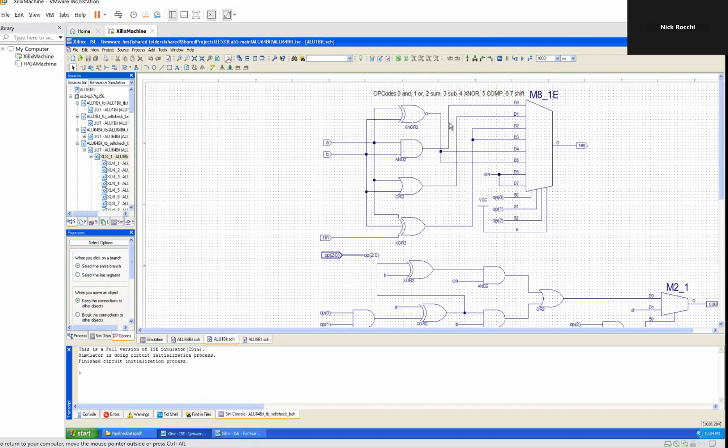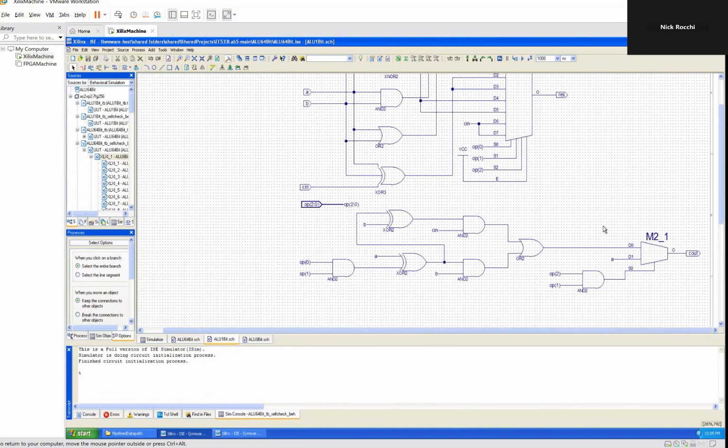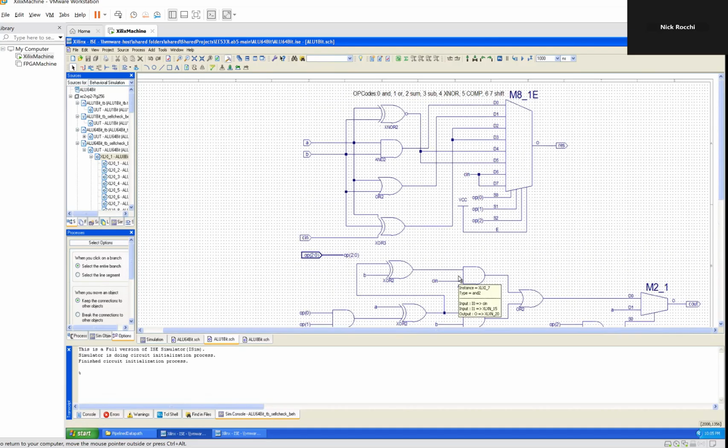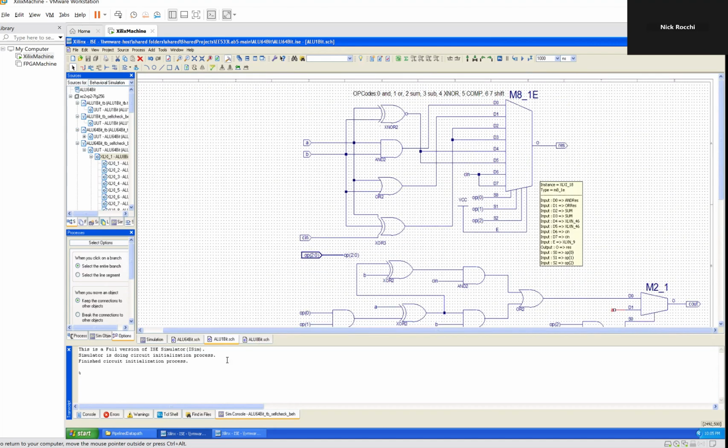We have all requested operations, as you can see. We take in 4 inputs, A, B, C in, and our operation, and output a result and a carry based on our needed results. It's worth noting that we have a setup here to see if we have a sum or a carryout for a sum or a difference of two numbers, and we have our input going to carryout for A in case we have shift. All other outputs go through the result.